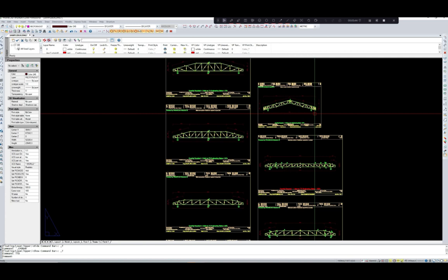So if you see AISI design example, it is only the movement about the major direction which is considered for design. The minor direction movements are very negligible whenever there is a presence of board on both sides. But the structural software will always analyze a bare frame, so it will develop movements about the minor direction.